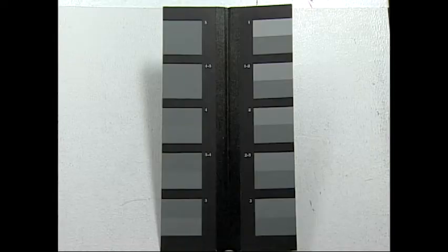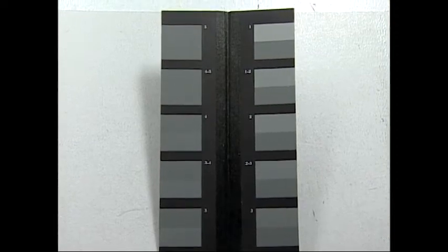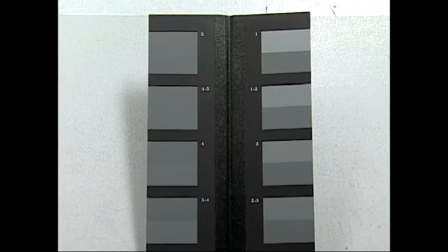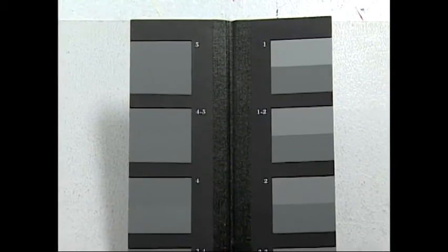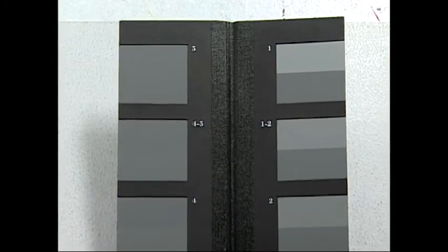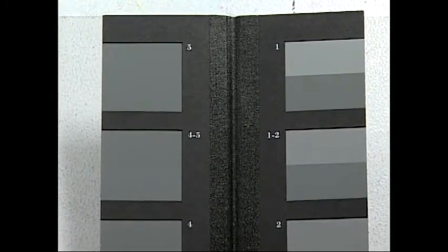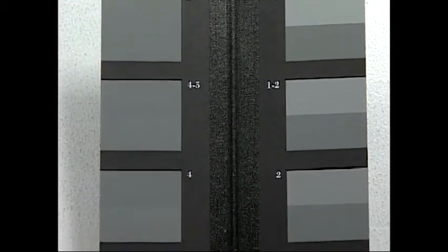A grayscale refers to the pairs of standard gray chips or tiles that relate to the corresponding numbers of the scale. The difference between pairs of tiles corresponds to its number value. In this procedure, the rating scale ranges from 1 to 5. In this type of system, the scale is linear, with a rating of 1 representing the greatest amount of change and a rating of 5 representing no change between the samples evaluated, or not enough to represent a 4 to 5 rating.